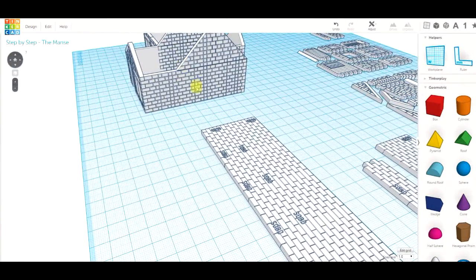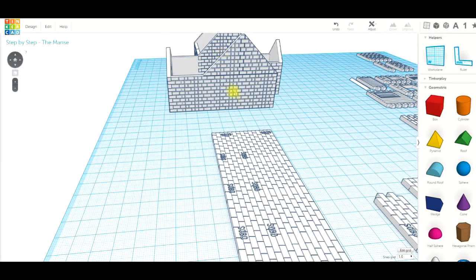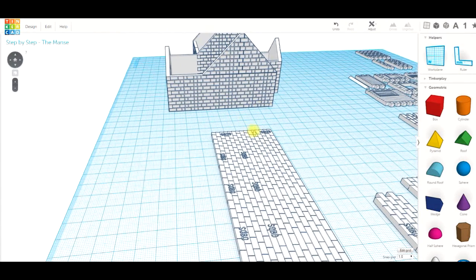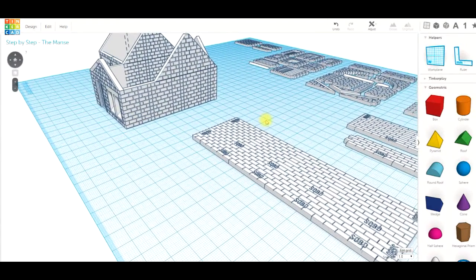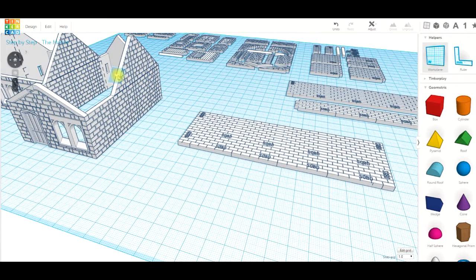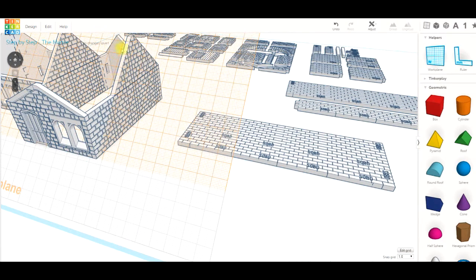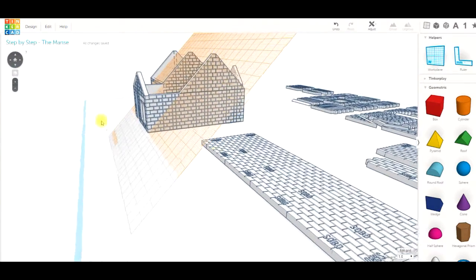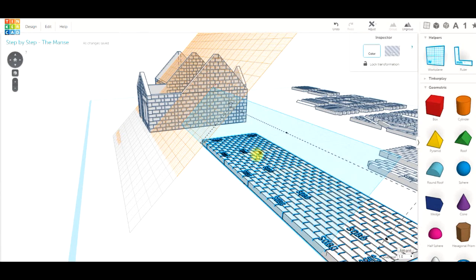Now we can go ahead and fit it onto the roof, as it were. You'll see that the second half of the roof is so much easier than the first. Okay, you remember the work plane tool again? We're going to work onto this top surface. I can't really see very well, so I'm going to move around. So we've cut through that roof plane. Click on this part.